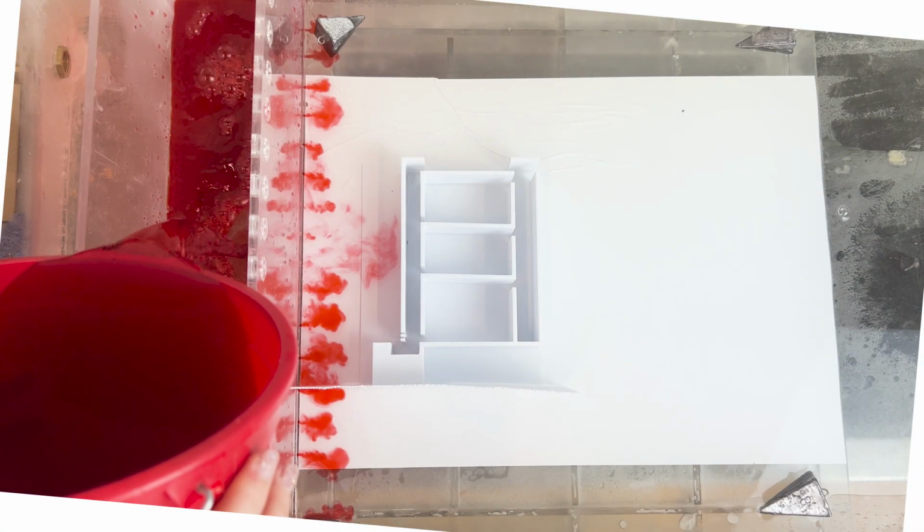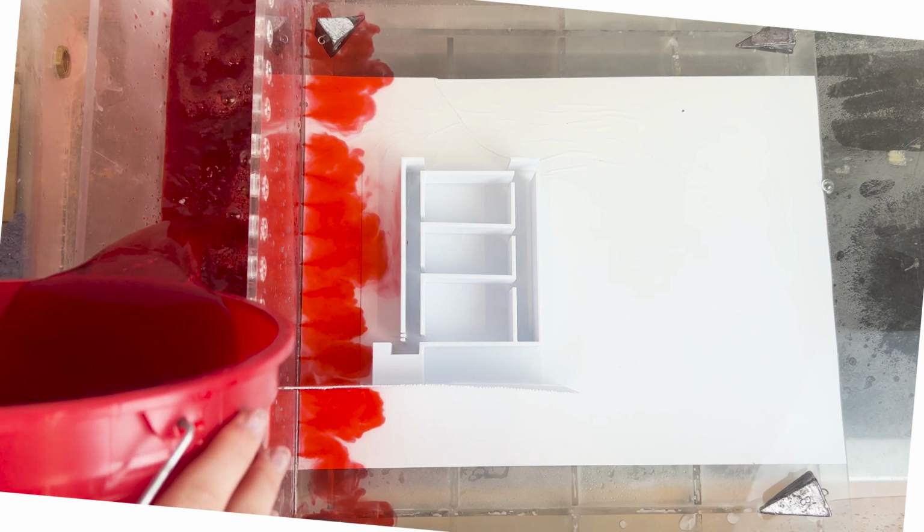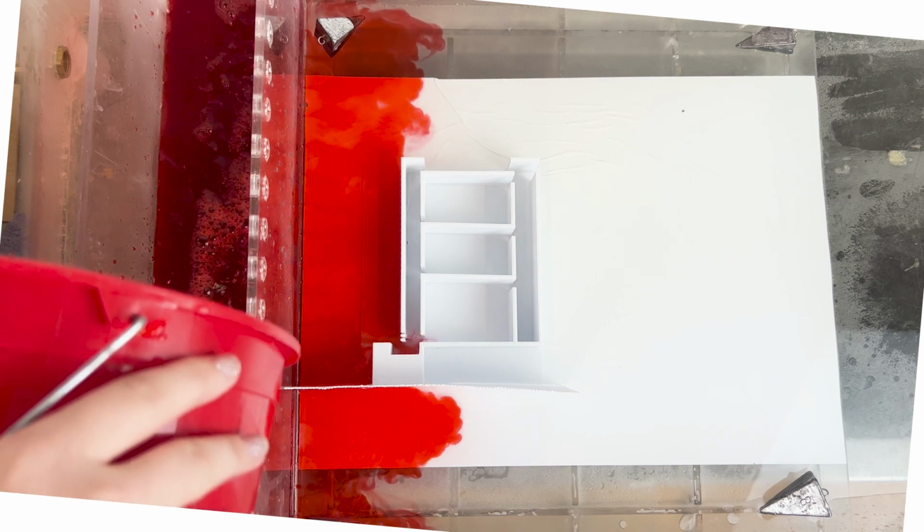This design test was performed in Massachusetts, and learning from our previous iterations, we tried to implement a ground floor plane to start to limit the amount of overflow of water that would come up and over these models. So that seemed to be successful in this test, which was good to see. When observing this, you can see how the double skin facade stops that initial flow of air movement and channels it down to that bottom channel and then up through the building. It immediately enters into those spaces, which is great to see.